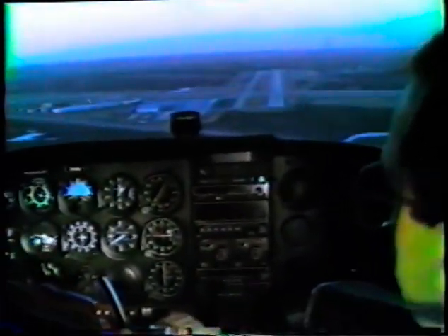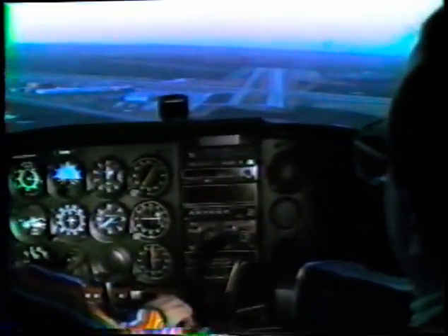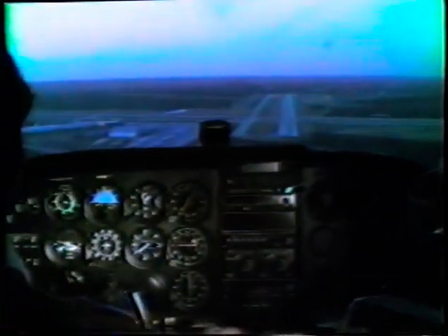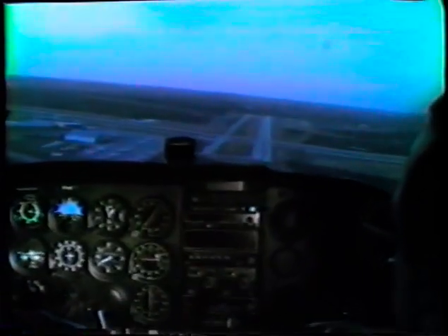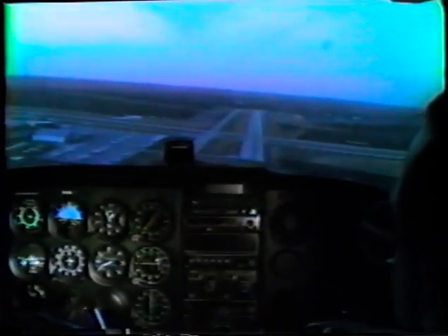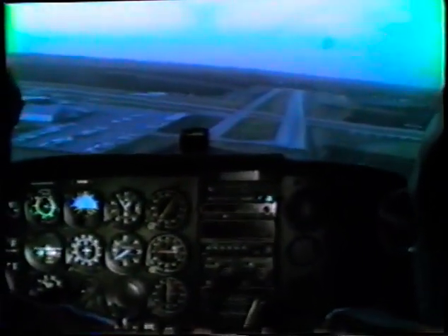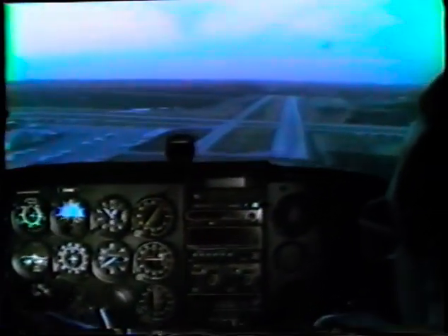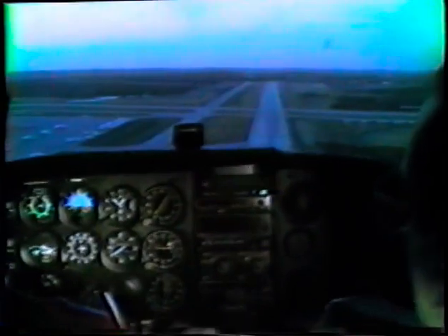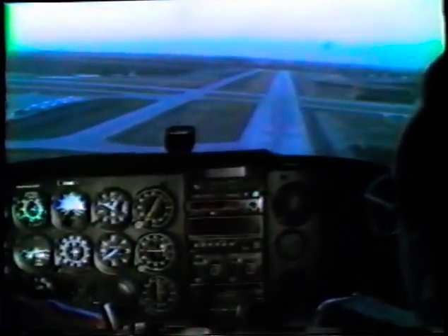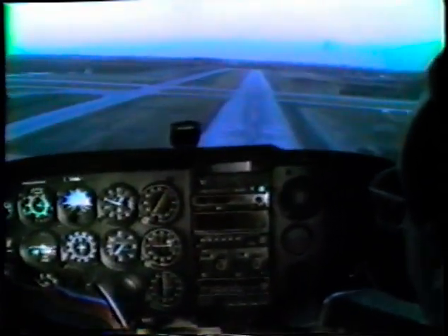A contact approach may be conducted even when the weather is less than VFR. It requires only 1 mile and clear of clouds and must be requested by the pilot. During a contact approach, ATC will provide IFR separation, but the pilot is responsible for obstacle clearance. If he cannot maintain cloud clearance or visibility falls below 1 mile, the pilot must immediately advise ATC and alternate instructions will be issued.